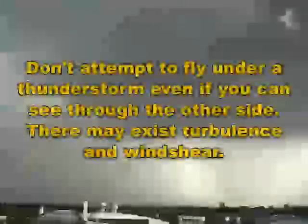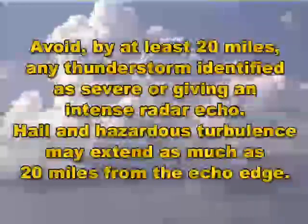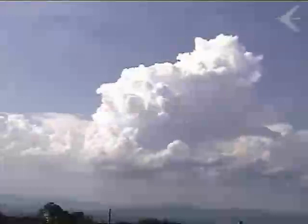Remember these tips regarding weather avoidance. Don't attempt to fly under a thunderstorm even if you can see through to the other side. There may be turbulence and wind shear. Avoid by at least 20 miles any thunderstorm identified as severe or giving an intense radar echo. Hail and hazardous turbulence may extend as much as 20 miles from the echo edge. It is better to avoid the whole thunderstorm area than to detour around individual storms, unless they are scattered.